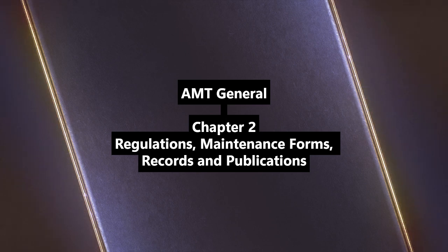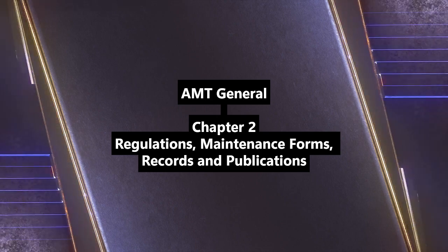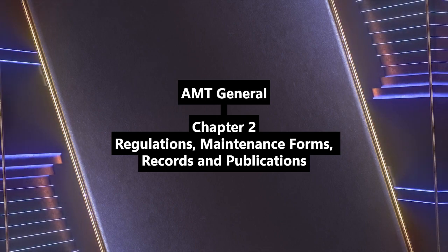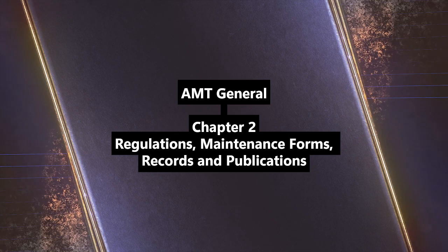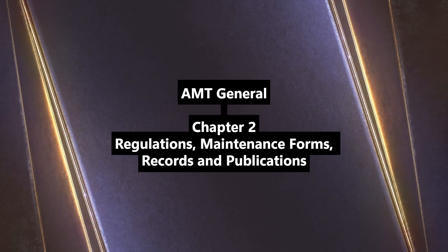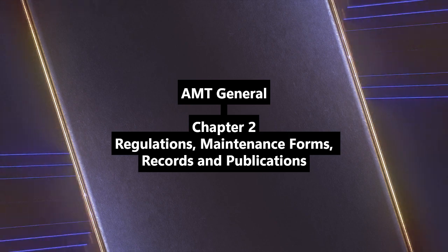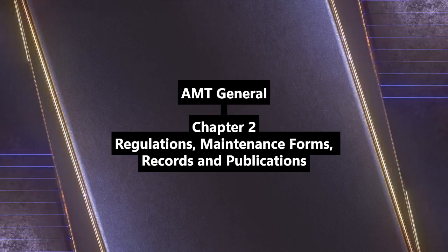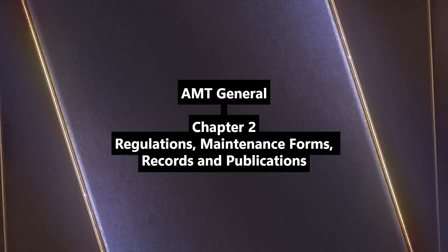So the key is always check the TCDS. Always. The type certificate data sheet tells you the specific certification basis. A Cessna 140 might be CAR 3 as a landplane, CAR 4A on skis. A Gulfstream G2 might be CAR 4B, but the GRA variant, Part 25, it varies. Okay, historical context is useful.